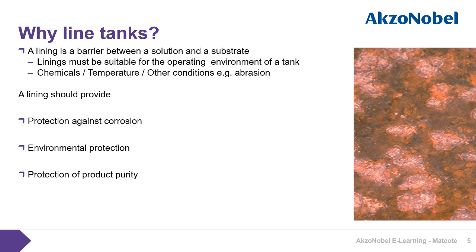A lining must provide protection against corrosion, as examples, crude oil tanks, the bottom and roughly 1 meter up the side, against corrosive chemicals such as aqueous solutions, against contaminants in refined products, and also the move towards biofuels has led to increased issues with steel corrosion.